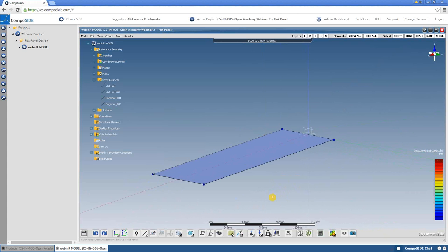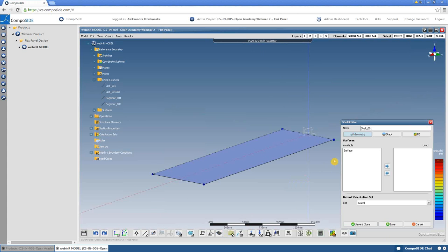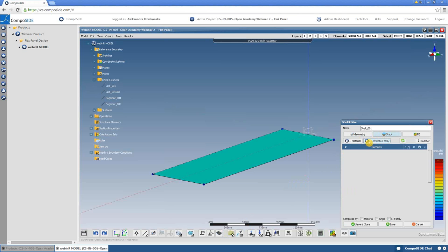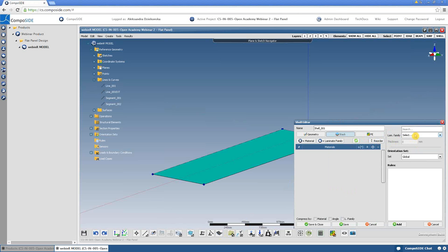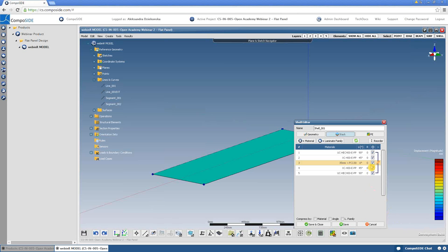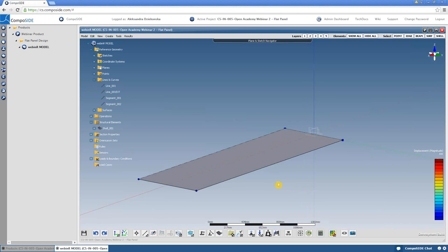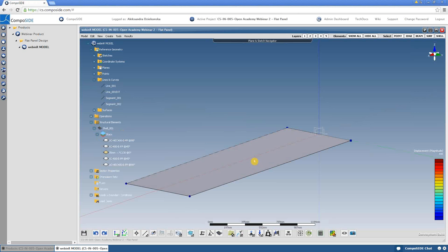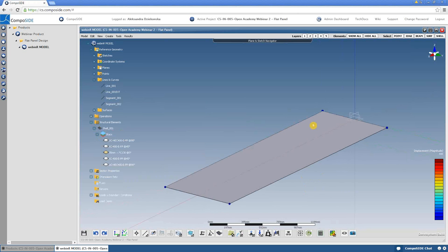So, as I mentioned before, now we're going to create a shell using this surface and using the laminate we've created in FESpace. Ola is bringing laminate from FESpace. The idea of shells is basically that you can collect different geometry and create one shell, apply one stack, and basically manage your stack for shell element, which is basically structural element.